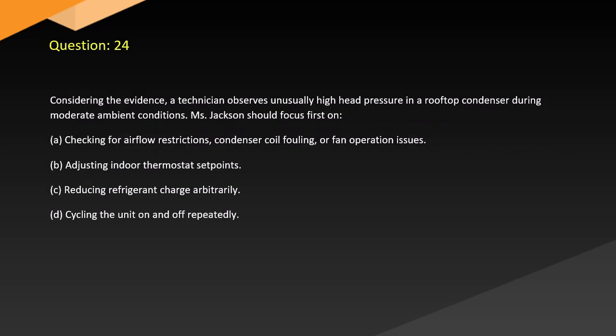Question 24. Considering the evidence, a technician observes unusually high head pressure in a rooftop condenser during moderate ambient conditions. Jackson should focus first on A. Checking for airflow restrictions, condenser coil fouling, or fan operation issues. B. Adjusting indoor thermostat set points. C. Reducing refrigerant charge arbitrarily. D. Cycling the unit on and off repeatedly.